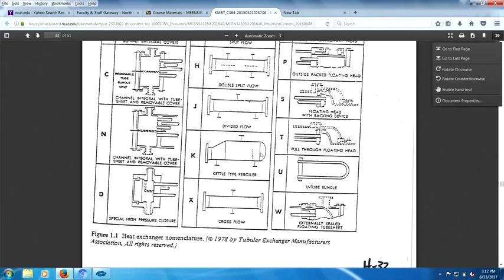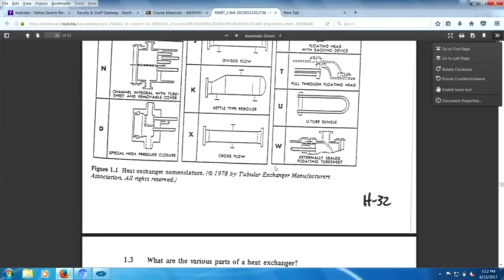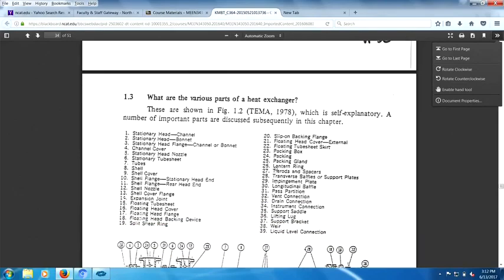Which for a reboiler wouldn't be a bad idea. U-tube, see that? There's no return bend there. Problem with U-tubes is bending the tubes such that they're not crimped. You ever try to bend a tube? It can be, how can I put it, quite humiliating. Give that to your children to see if they can do it.